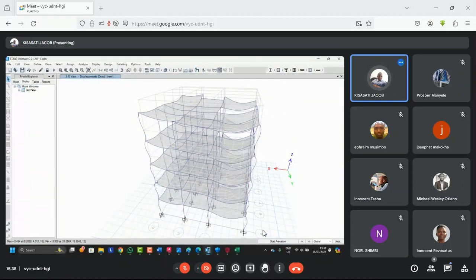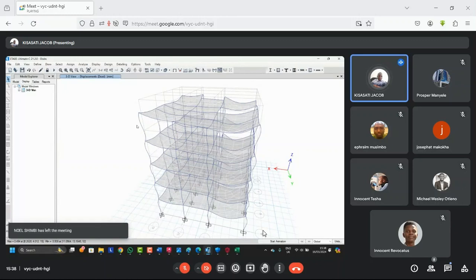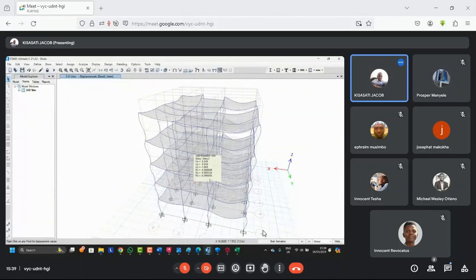You will learn about these. This bending of the column is now the creation of moments in the column. Moments are created in columns in different ways. One, eccentricity. You learn about eccentricity. Two, column orientation. Then three, lateral loads, the wind, the earthquake. All those things will create eccentricity. So it depends on how you are going to join at these points. When you never commit, it will be very simple. You can also run an animation of the building to see how it behaves under dead load.